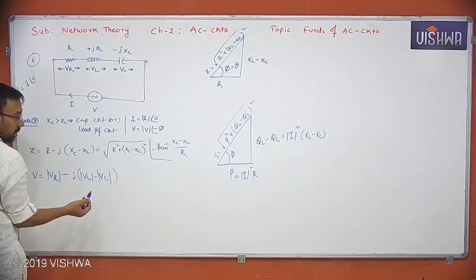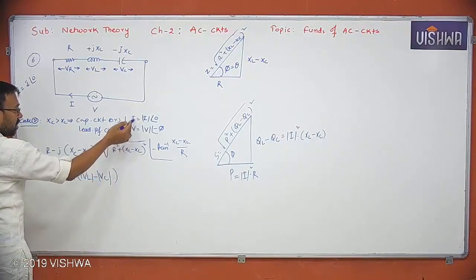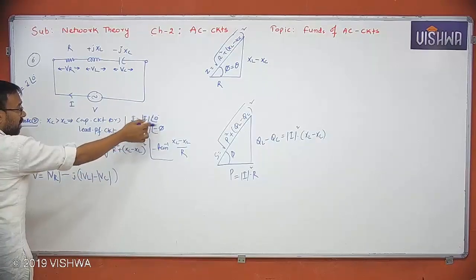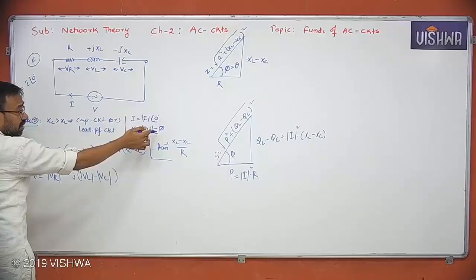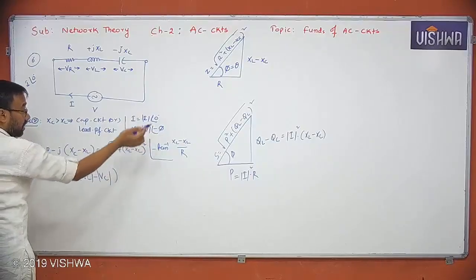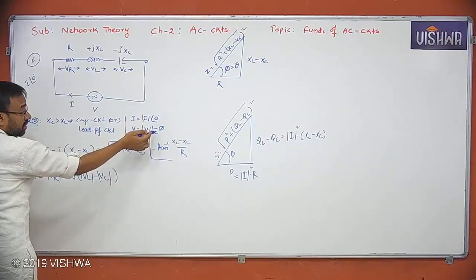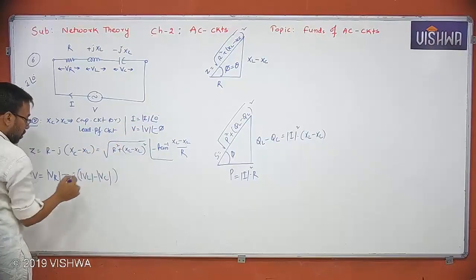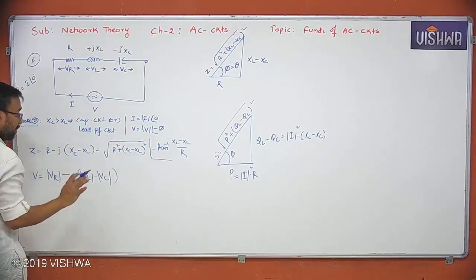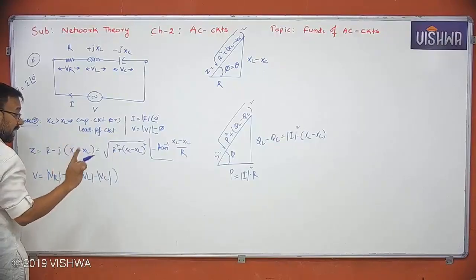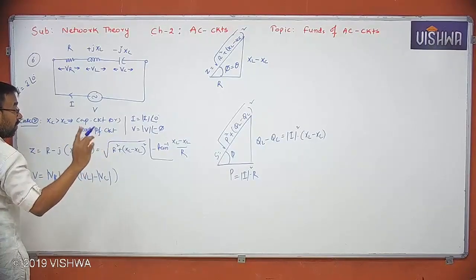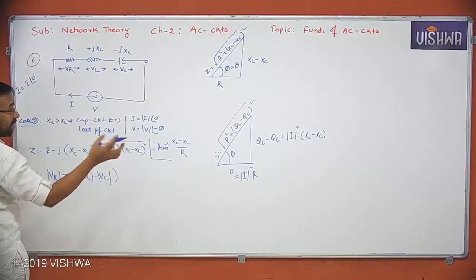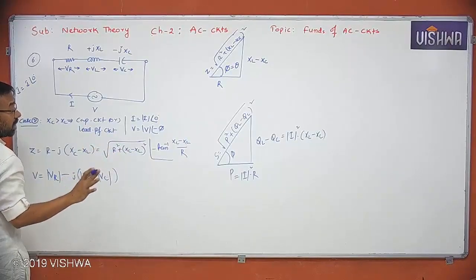Understand? But to satisfy the condition here, current leads voltage, I can take n number of combinations. This is 60 degrees, this is 30 degrees, since both are positive values. This is 0 angle, this is minus 30 degrees, that means this is positive, this is negative. You understand? So it need not be negative. For voltage and current I cannot say, but I can say for Z, Y, and P. So which form are you going to get, A plus jB or A minus jB? For impedance, admittance, and power I can decide, but for voltage and current I cannot. It all depends.